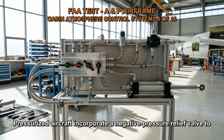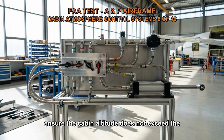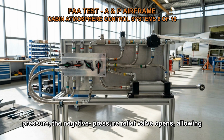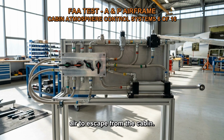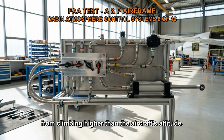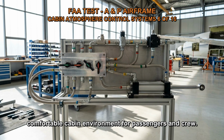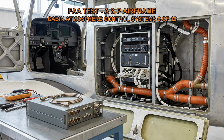Pressurized aircraft incorporate a negative pressure relief valve to ensure the cabin altitude does not exceed the aircraft altitude. This valve can be integrated into the outflow valve or exist as a separate unit. When the outside air pressure exceeds the cabin pressure, the negative pressure relief valve opens, allowing air to escape from the cabin. By doing so, it prevents the cabin altitude from climbing higher than the aircraft's altitude. This safety feature helps maintain a controlled and comfortable cabin environment for passengers and crew.